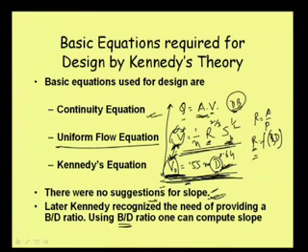Now, when we use the B by D ratio, what we can do is assume a D. From that we get a V, and from the B by D ratio we will also get a B, and using that B we can directly see whether, if we adjust the slope with that B and D value, we can get this velocity.